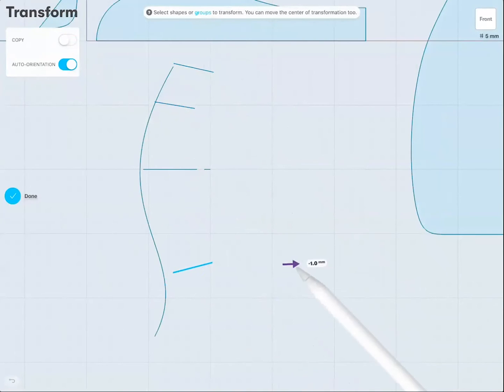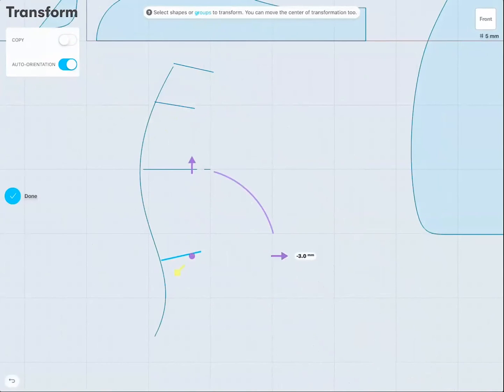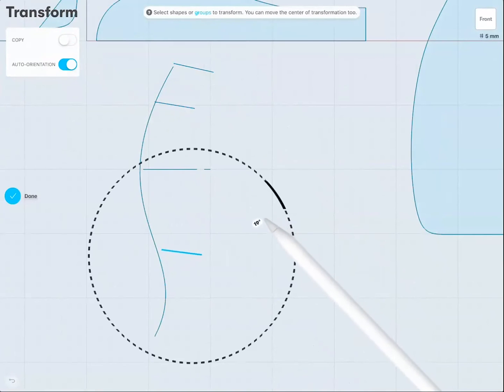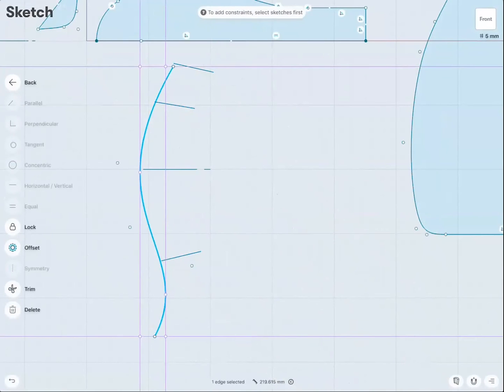You see, that is the reason why I created this spline. I try to rotate these profiles so they touch the spline somewhat perpendicularly. If they are rotated more like this or like this, that is not ideal. So I want them to be perpendicular to the spline.